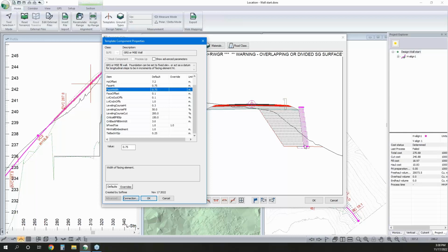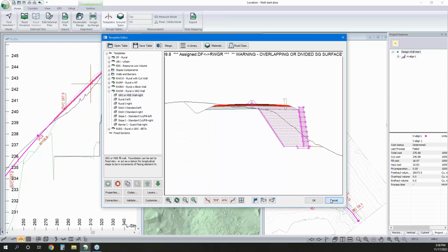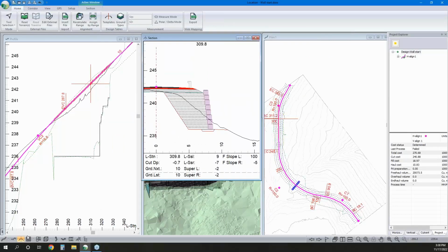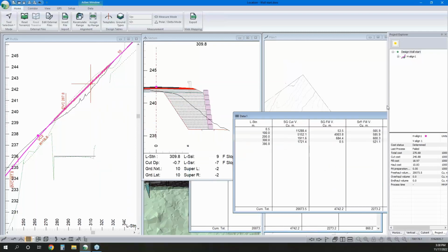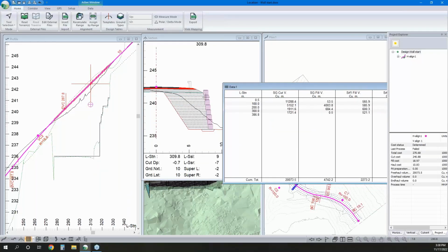Okay. The next one that we have is, how do you get the quantity or volume of blocks needed in the project? All right. So we could come down here, create a data table. I've got data tables with different unit volumes in them. First step is to figure out what volumes we'd like to report.